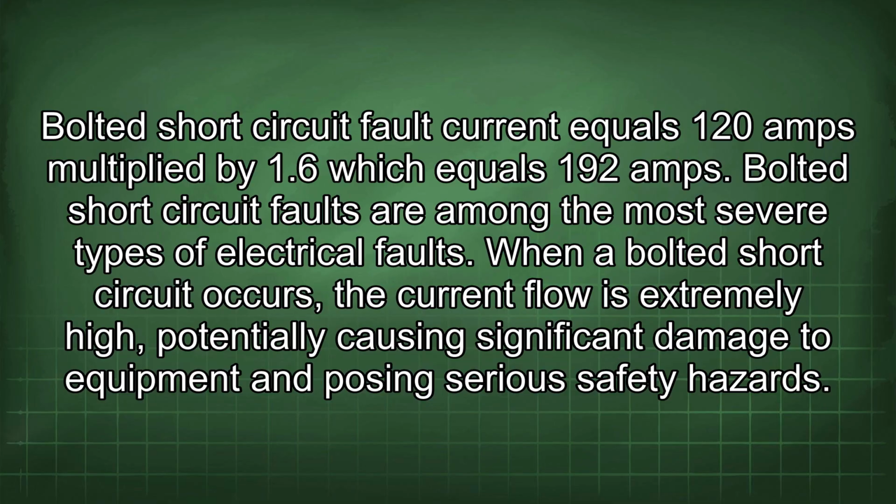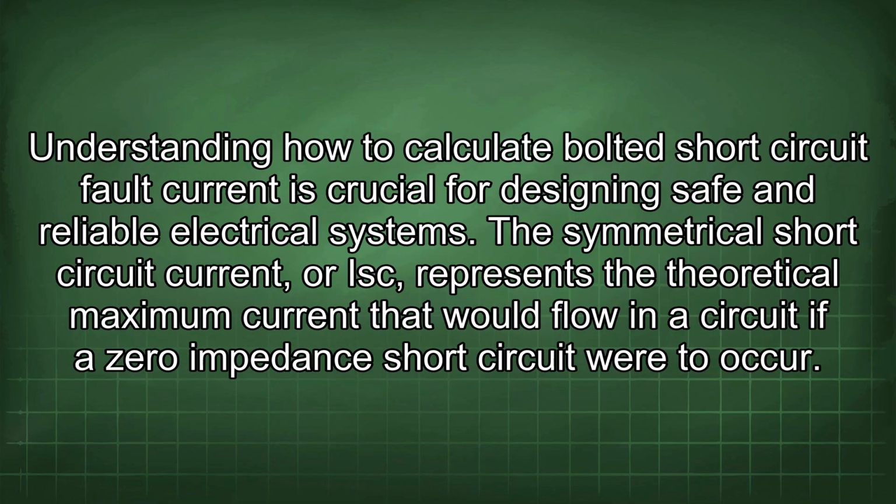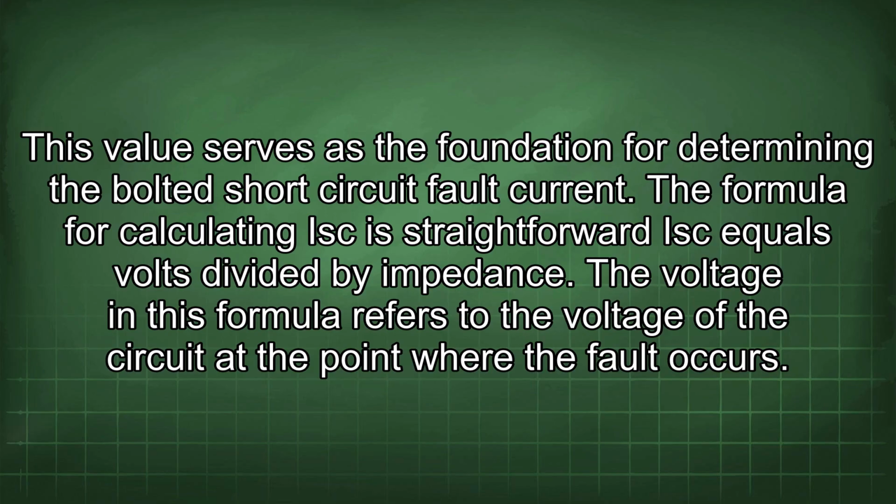Bolted short circuit faults are among the most severe types of electrical faults. When a bolted short circuit occurs, the current flow is extremely high, potentially causing significant damage to equipment and posing serious safety hazards. Understanding how to calculate bolted short circuit fault current is crucial for designing safe and reliable electrical systems. The symmetrical short circuit current, or ISC, represents the theoretical maximum current that would flow in a circuit if a zero impedance short circuit were to occur. This value serves as the foundation for determining the bolted short circuit fault current.